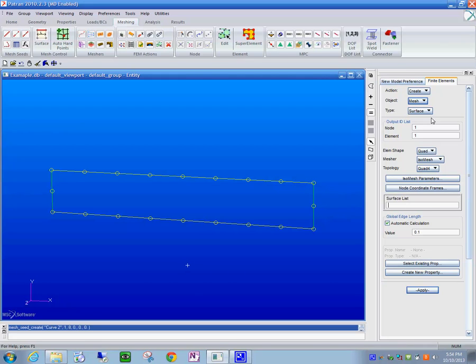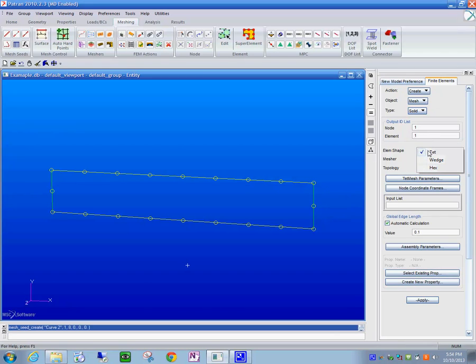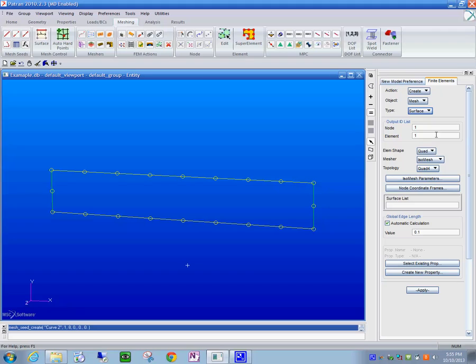You see, by default, when you select a surface, the computer gives you two-dimensional elements. If I had a solid here, it would give me other choices of elements: wedges, hex elements, things like that. But let's keep in mind, I don't want to confuse things. This is a 2D surface, with either quad elements or triangular elements. So we're going to go with triangular elements. And at this point, we need to pick the surface.